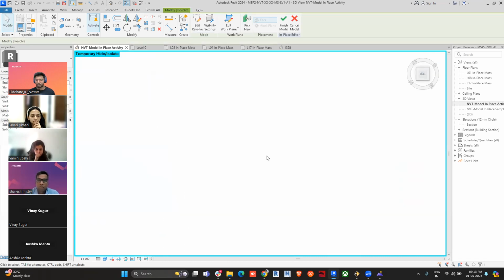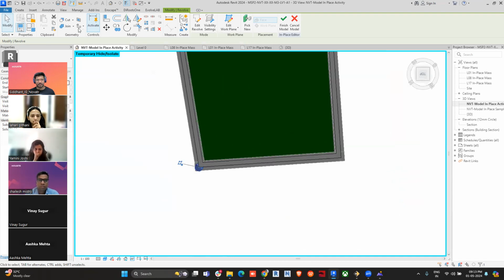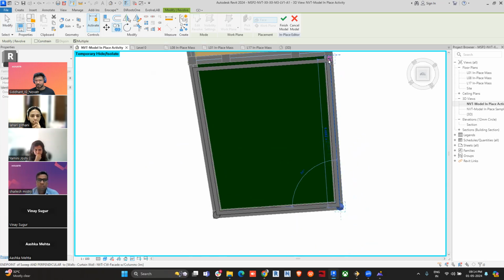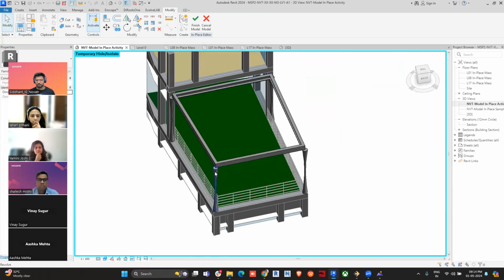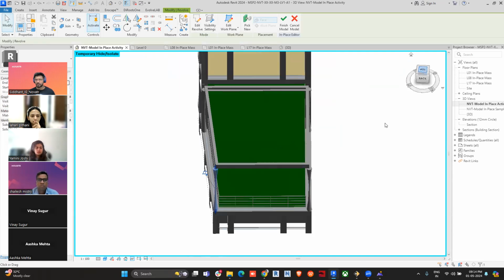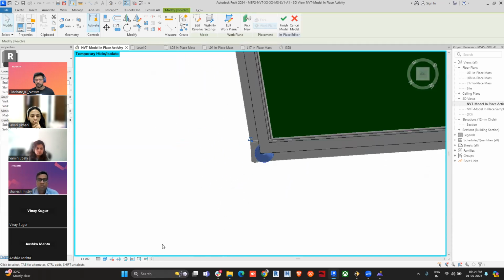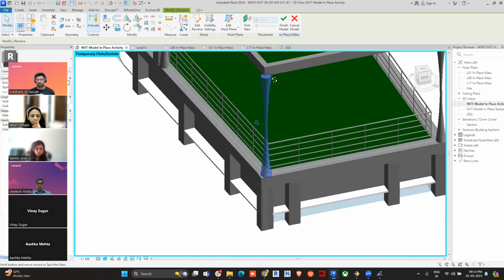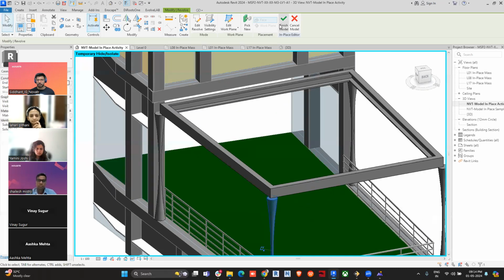You can just go to top, or you can copy paste elements, right? So I'll use the copy paste tool over here. Copy, put to this point. I think one more over here and one more over here. So we have 4 columns. You can adjust it on the top. You can just move it in, move it out, and work around wherever you want. So that is totally up to you.